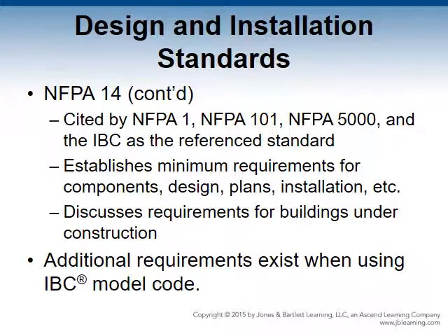When designing a system based on the IBC model code, additional requirements do exist, such as the location of the standpipe hose connections, protection of risers and laterals, interconnection, control valve supervision, and cabinet identification and security, to name a few.